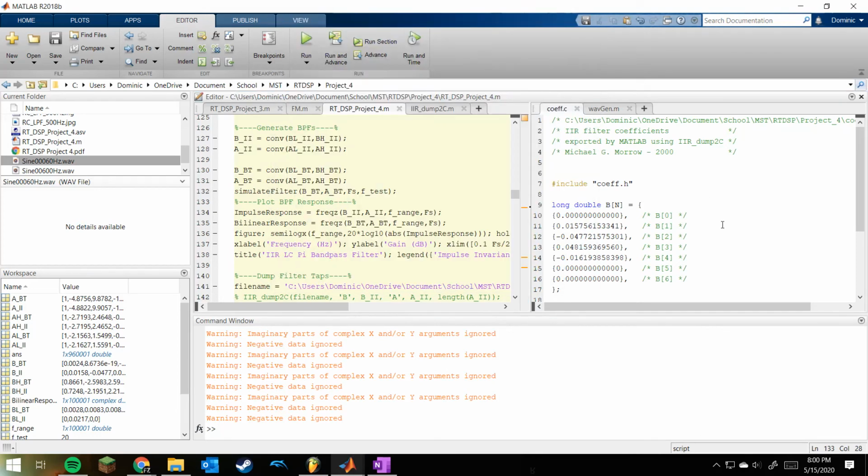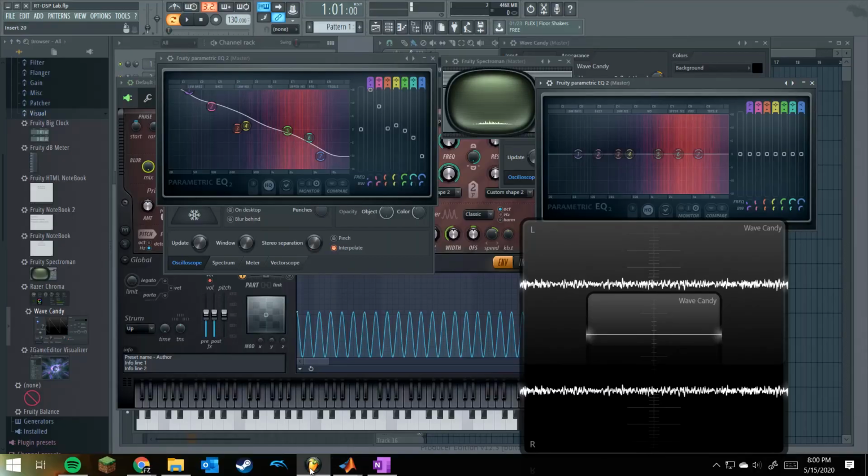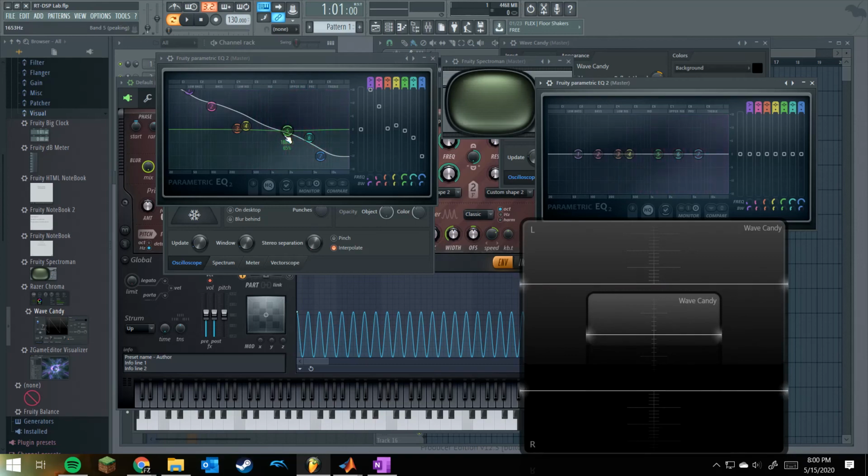we're going to go ahead and generate these coefficients. These are the bilinear transform pair coefficients. And if you look at MATLAB, you should expect something that already looks like this, because this was the impulse invariance one. So let me flash the DSP board with the new filter, and fingers crossed we don't get any NaNs this time.